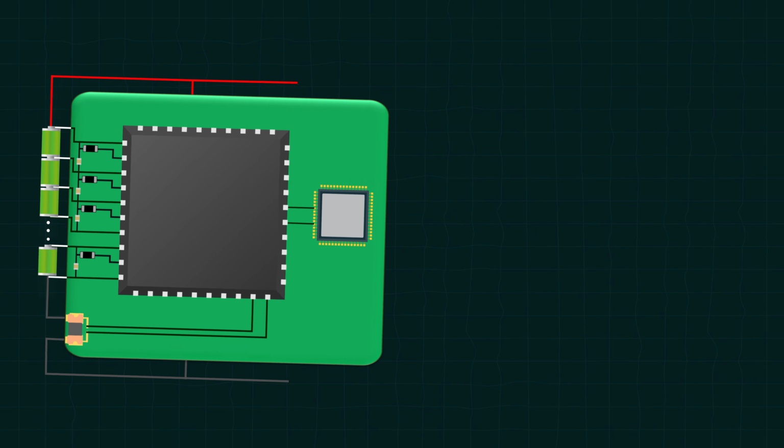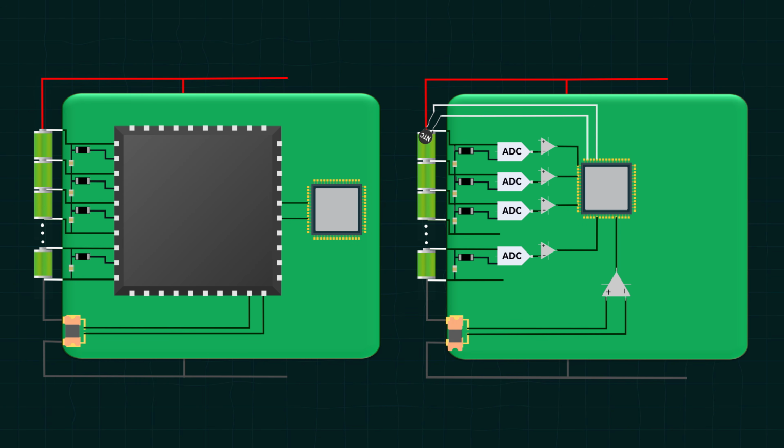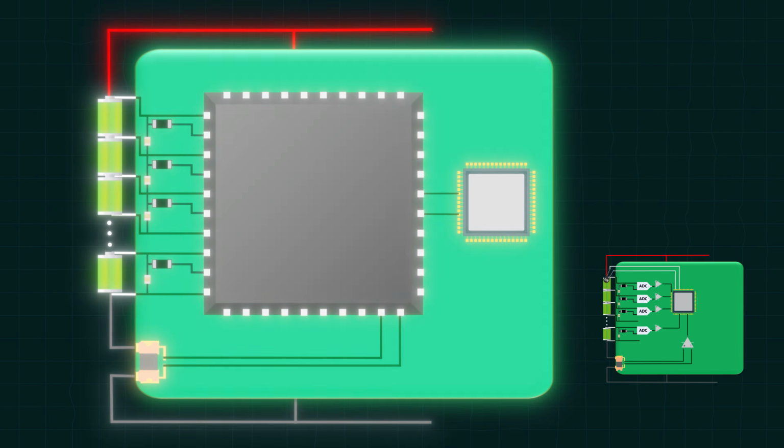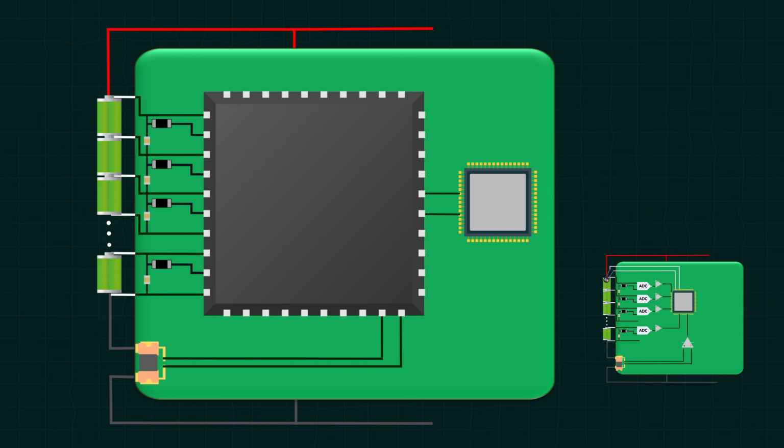So, while in principle we could build a BMS analog front end from scratch, in practice, using a dedicated AFE IC is a no-brainer for anything beyond the simplest systems. It's more precise, safer, and ultimately cheaper when we factor in the design time and component count. That's what makes AFEs so special compared to generic ADCs or comparators. They are the specialized multi-tool for this job.